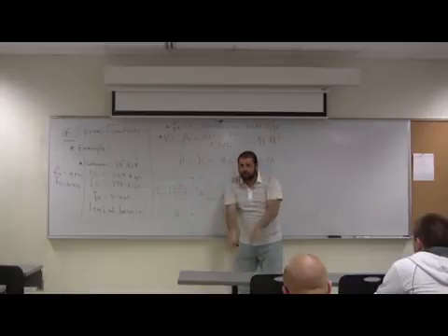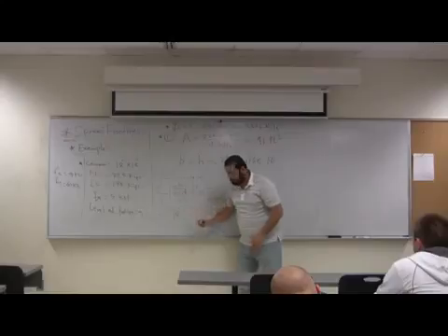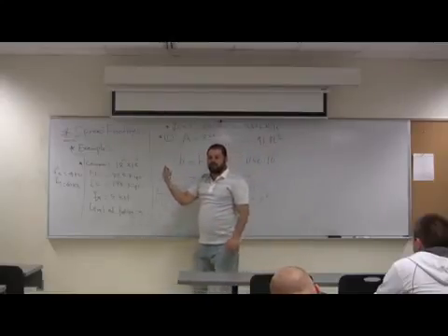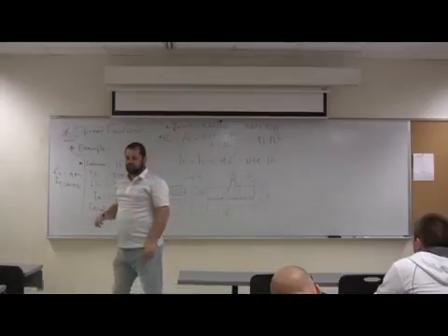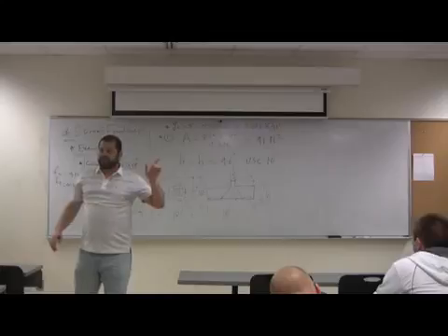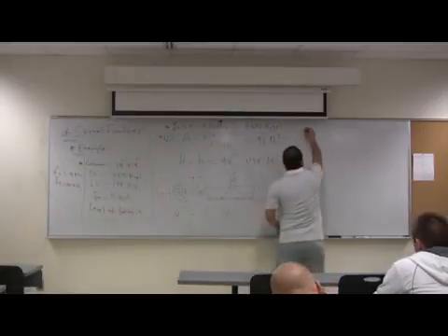That box will go like that. How much is this distance from here to here? D over 2 all around on the four faces, D over 2 from the face of the column. That's what we call the perimeter for punching. They have this designation for it.